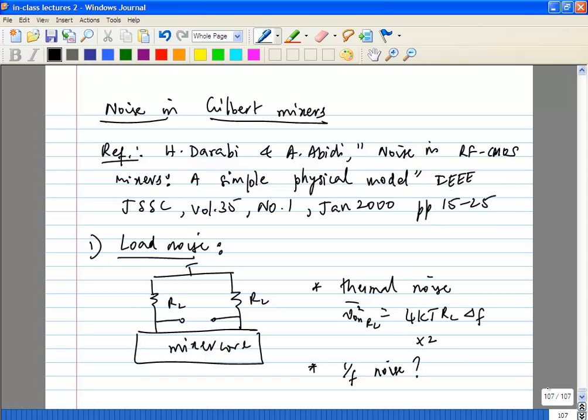What are the issues with this? We discussed this last class. Your voltage gain is proportional to the resistance, but your headroom is inversely related. It's basically VDD minus I_D times RL, that's the headroom which you're losing. As you keep increasing the current, as you keep increasing the resistance, the output DC bias keeps dropping. So that's a problem. Okay.